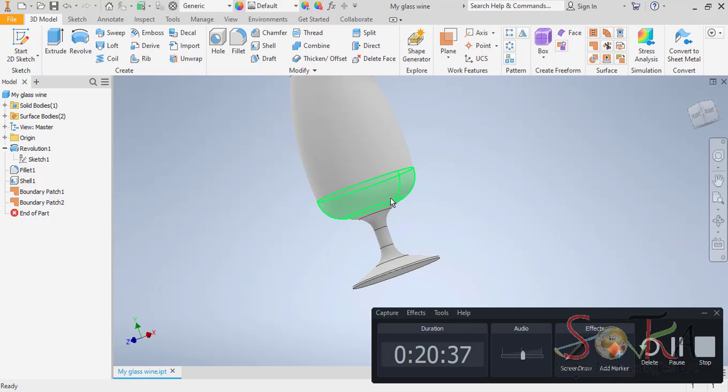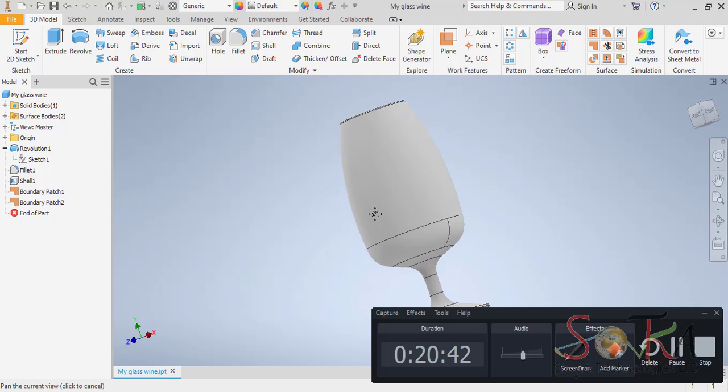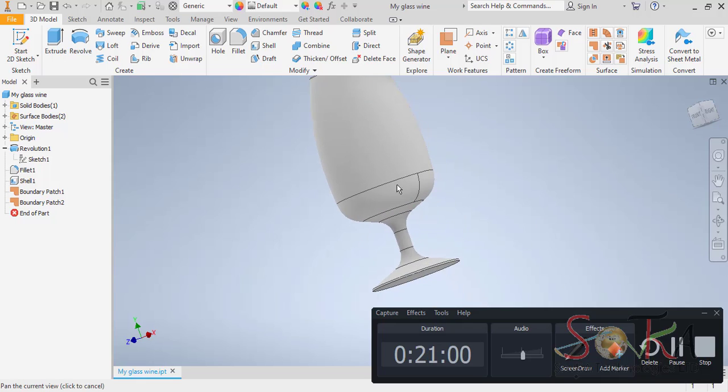Beautiful. Wow. Now I've patched, but again I need to fill in, because someone else would have used a different command, like, let me say, extrude, to create this stalk and also shape it into that position by maybe lofting it. But that's a long process. The easiest I prefer is just to sculpt it and fill the gap in there.